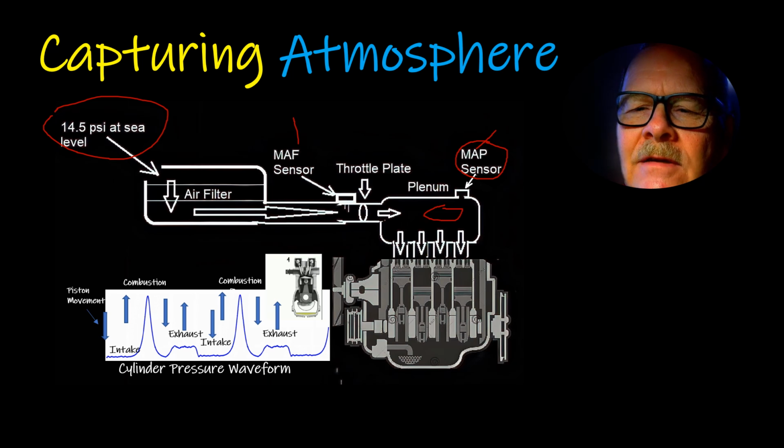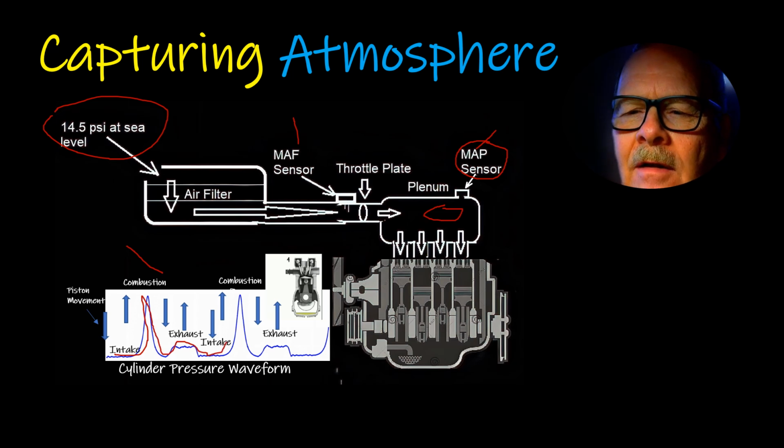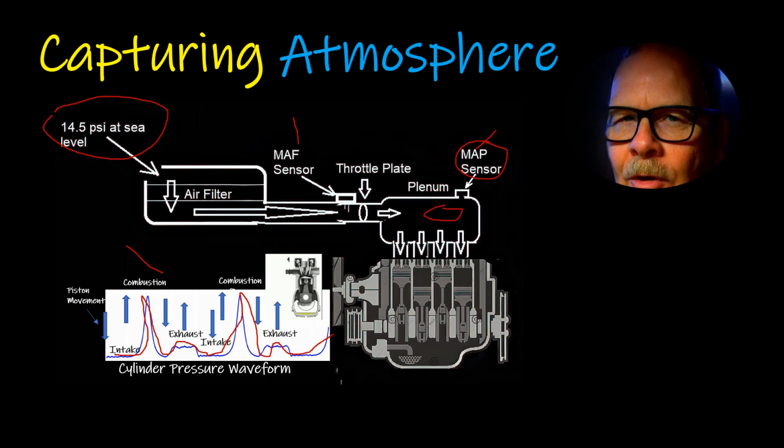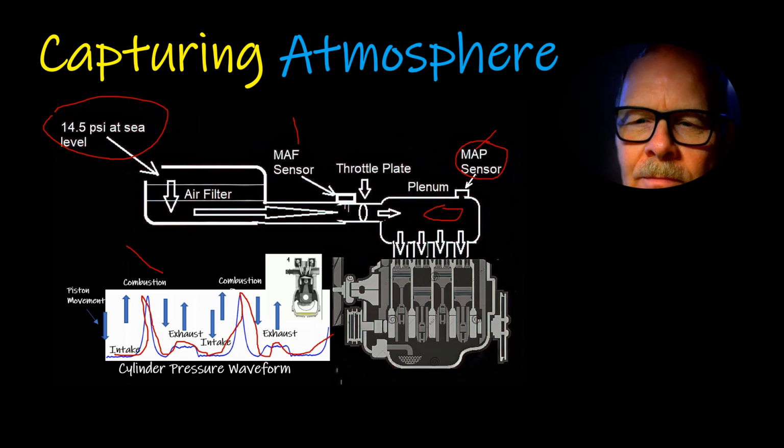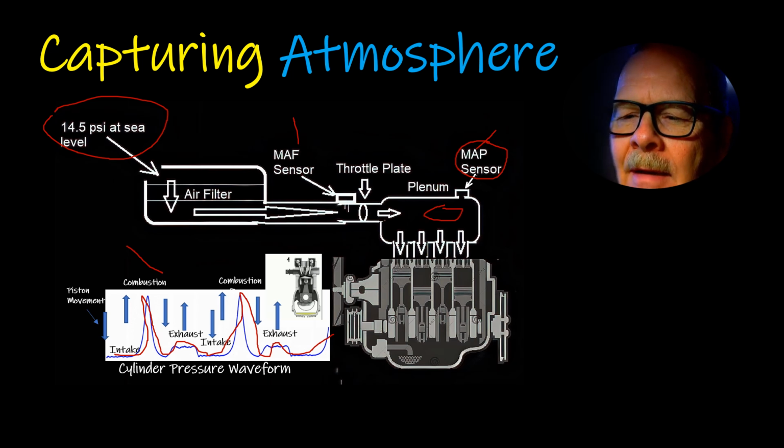And then your piston movement. This is the waveform down here. This waveform that you see right here is the waveform that you get with a transducer screwed into a spark plug hole, so that you're reading off of that one and the engine's running and all that. A spinning engine, if you've got your transducer in there, this pattern won't look like this if the engine's just spinning. It has to be running. So you might want to keep that in mind too.